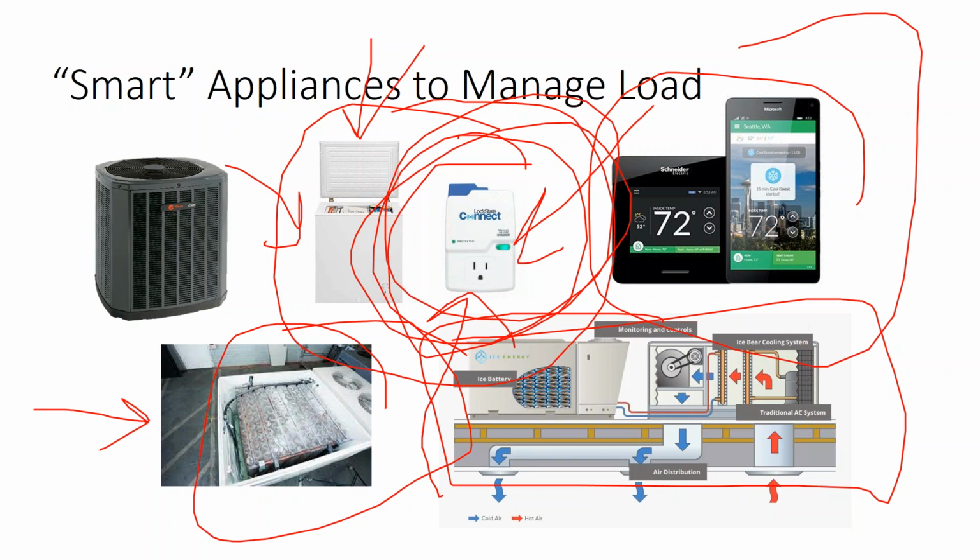So there's a lot of smart energy management devices, and it might be the onus of the solar installer to say, now that arrays are getting more expensive, and we're getting into right-sized arrays that are a function of the building load, maybe we take on more scope in terms of managing our on-site energy and seeing what loads the client has that we could push into times of solar production and take out of times of non-production.